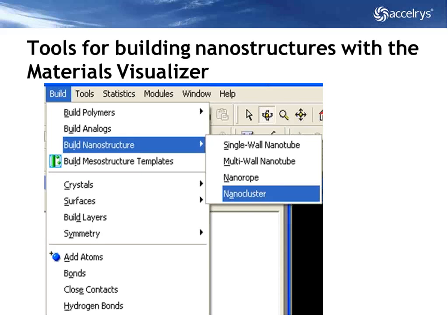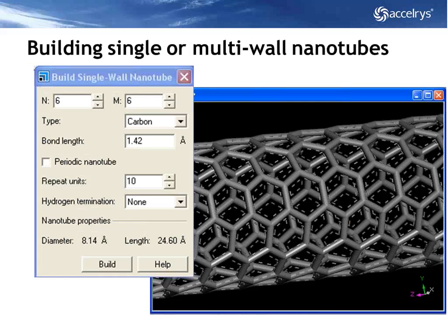Things like nanoclusters, you have to have an input crystal structure, and then that becomes defined by the nano builder. You can build frustrums, you can build polyhedrons, you can build dumbbells, cylinders, squares, cubes, spheres, etc. So here I'm defining again by n vectors, whether I have a chiral system or an achiral system, right? You can hydrogen terminate your chain. If you wish to build caps, we actually, on the accelrys.org community website, there have been a number of people posted mechanisms or methods or approaches, both script-based, force field-based, geometric-based, for capping these with rounded caps and systems.